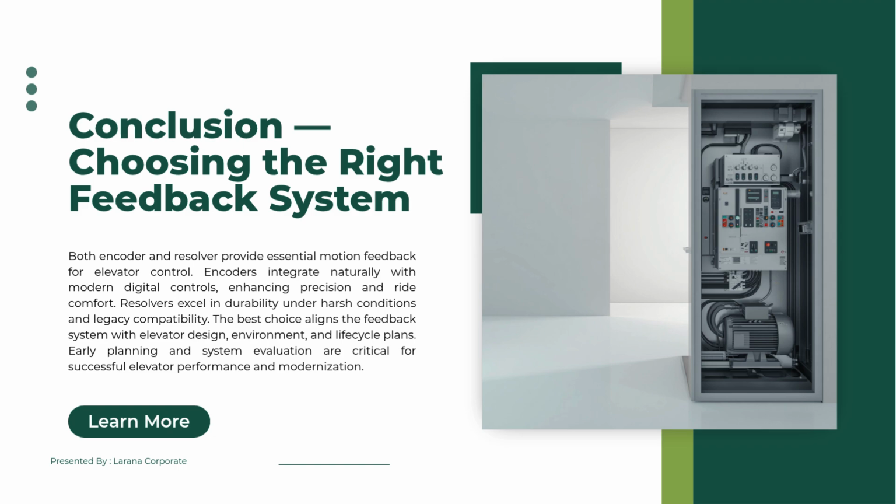If a modernization team upgrades to a PM motor or a modern digital controller without reviewing the existing feedback system, the project may face longer commissioning time, tuning problems, signal mismatch, higher retrofit cost, increased downtime, and more difficult maintenance. That is why feedback architecture should be evaluated early in modernization planning. It should not be checked only after the traction machine or controller has already been selected.